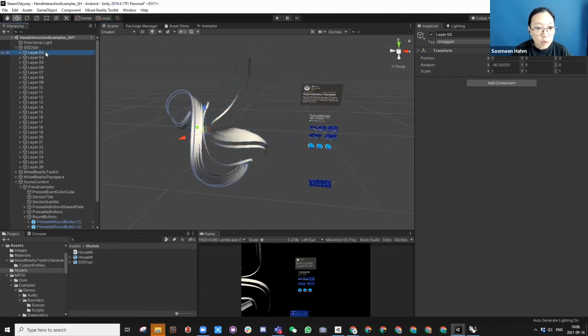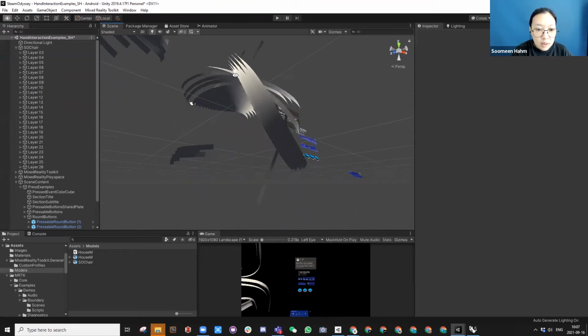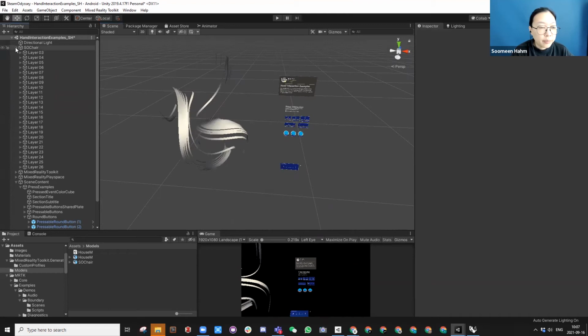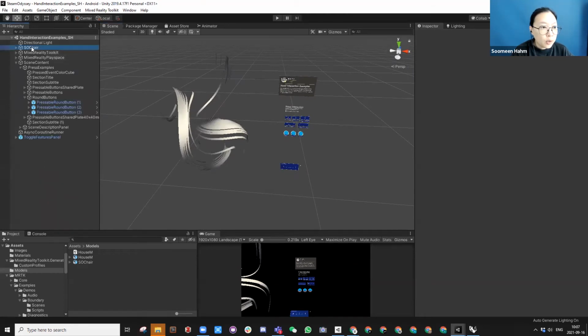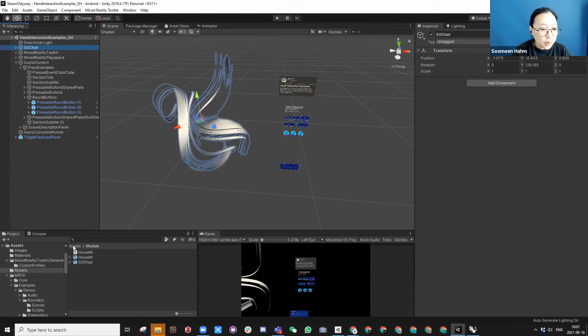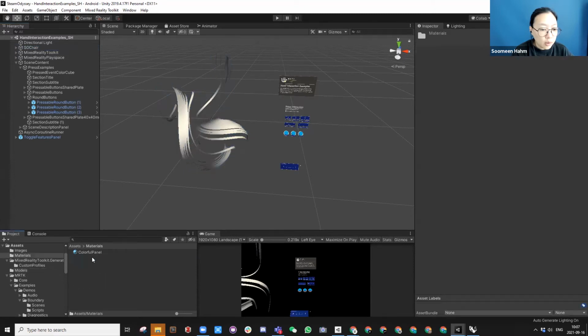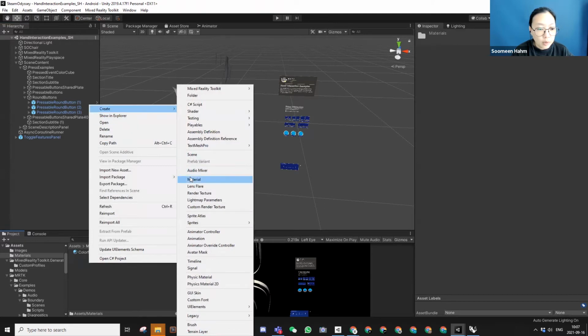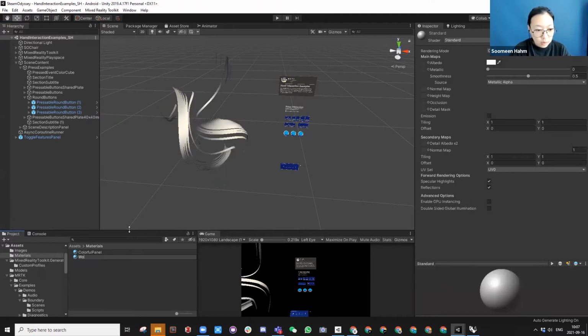That's great. And we know that we already set all the parts. In Unity, it doesn't display double side, so it looks really weird. So we are going to use a shader to display this. We are going to use a new material. We are going to make a material called wood double side.